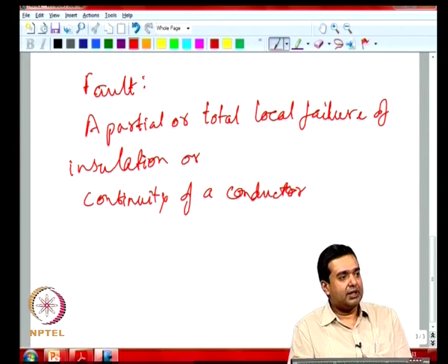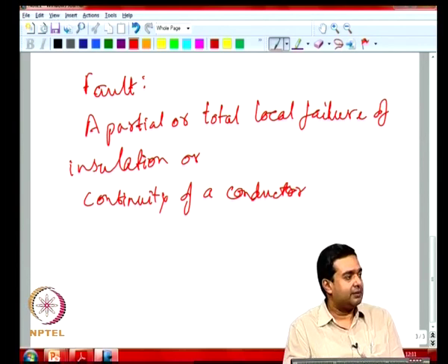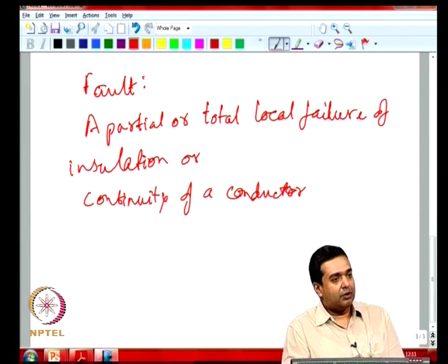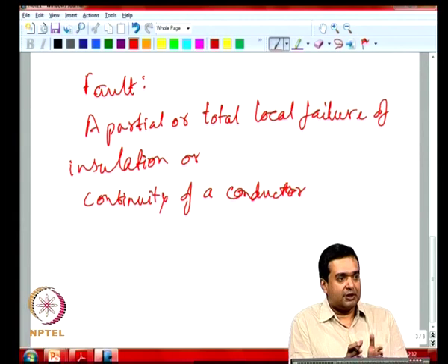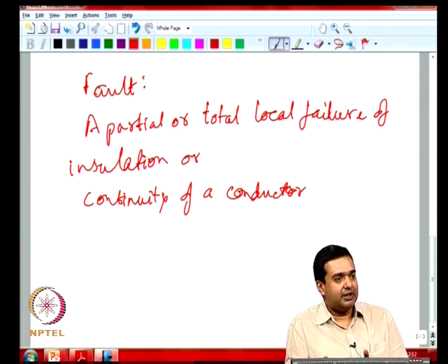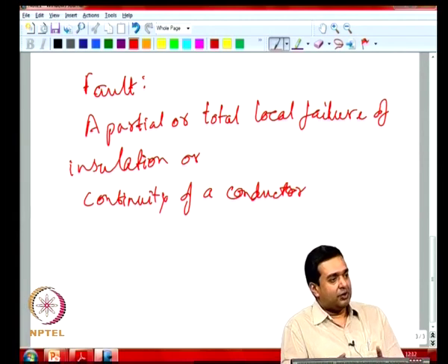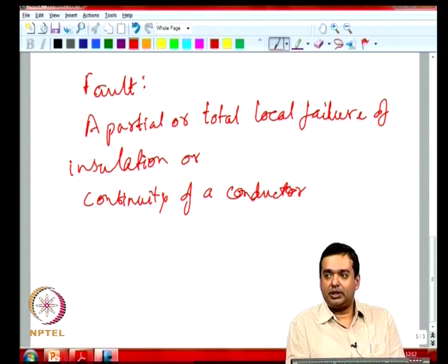For example, if you look at over voltage, what commonly comes to our mind would be lightning striking a line. But the interesting thing about lightning striking the line is that if it strikes a section of the line, then you would end up having over voltage in a small section of the line or the feeder, and you would have surge arresters, over voltage protection components which are situated close by.